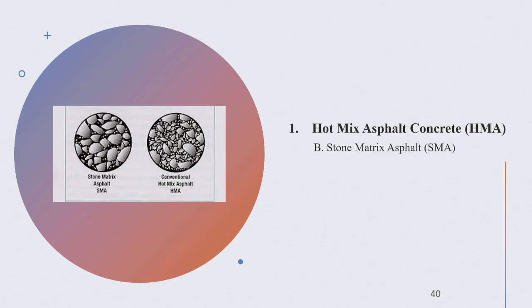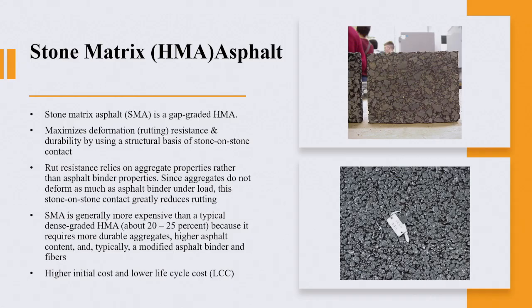So the sellers of roller compacted concrete tell you, yes, it might cost you more, it might ask for more trucks to transfer, but you might end up eliminating all the steel bars which you use in resisting temperature change. So a lot of the projects done with roller compacted concrete are pure, plain concrete, no reinforcement. You don't need shrinkage rebars. So that drops the price. It offsets a little bit the cost you incur during your transportation.